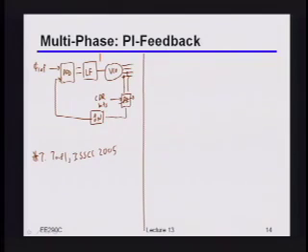So, ideally, the phase should be locked to quadrature or something. Or depending on the lock point, you can probably insert some offset into the comparison between the two phases. Okay, you could do that. Remember, I want a full 360 degrees of range, and I want to do that in a fairly transparent way, but you're absolutely right. I could just somehow muck with the phase frequency detector to adjust its offset.